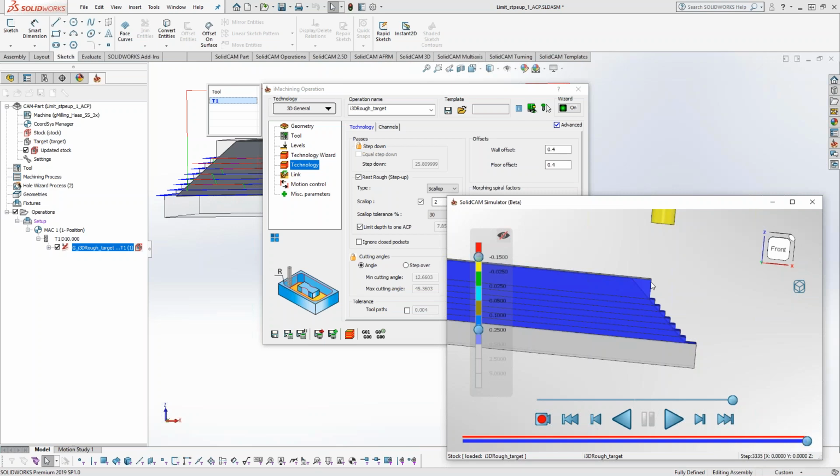But those tools are a little bit more sensitive when it comes to chatter, because the flutes and everything are meant to be a little bit more sharp. If you get a general purpose end mill, or even a bull mill, just taking an end mill and putting a small corner radius on it helps with the abuse that the tip of the cutter takes. So you can choose what tool removes this remaining material.